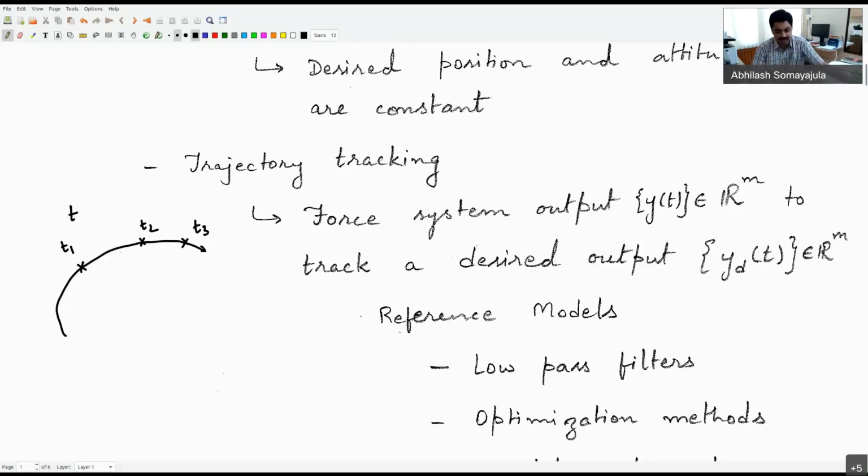So for example, if I took a ship and said you start from 0 speed and then suddenly execute a maneuver like this and go forward, I can't execute a maneuver sideways. It's simply not possible because the ship does not have a mechanism with which it can translate in this direction, right? So if I give it a trajectory like that, such a trajectory cannot be tracked.